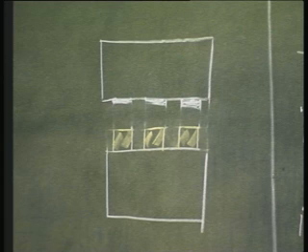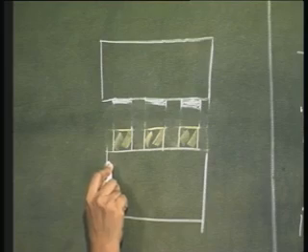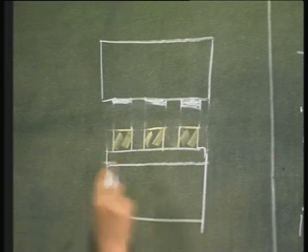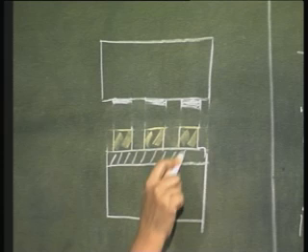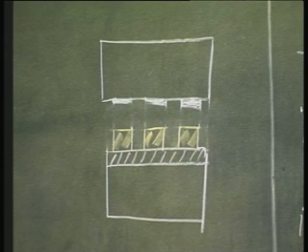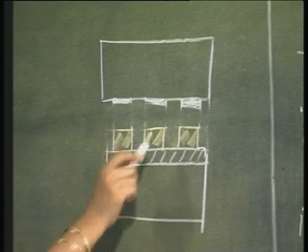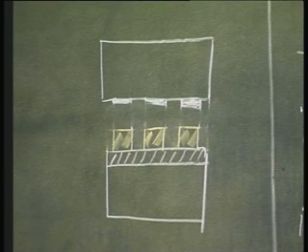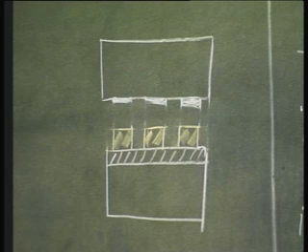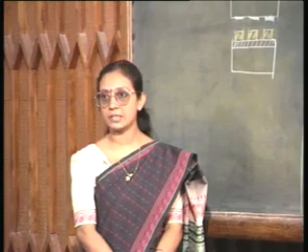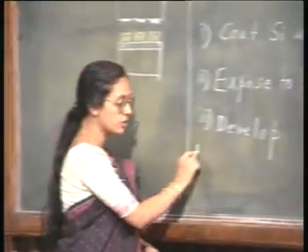Do you see? So, now I have transferred the pattern from the mask onto the resist on top of the silicon wafer. Agreed? Now, in most cases this wafer will have an oxide on its surface, on the surface on which we coated the resist. So, this is silicon dioxide, this is the underlying silicon, and on top of that I now have the pattern in photoresist after developing it. Now, what do I do? I put it in diluted HF etching, that is the fourth step.